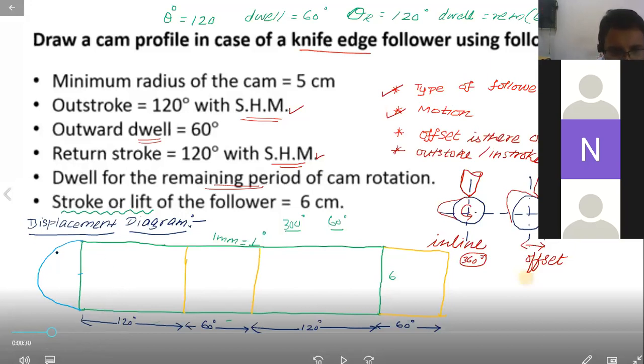And this we are dividing into 6 equal parts now. How to divide this semicircle into 6 equal parts? One method is 180 divided by 6. You can use a protractor, mark it, and then put the line. Another method is,